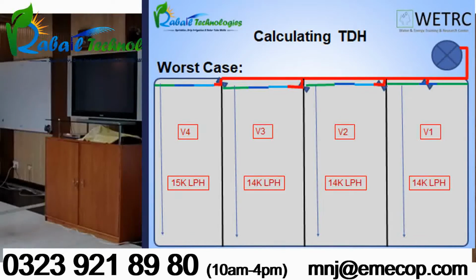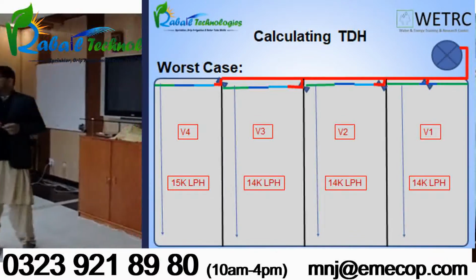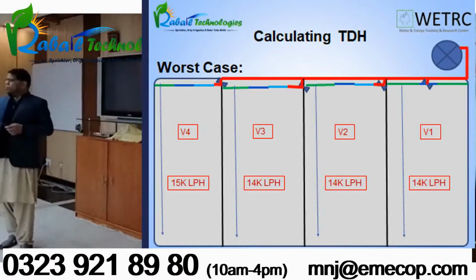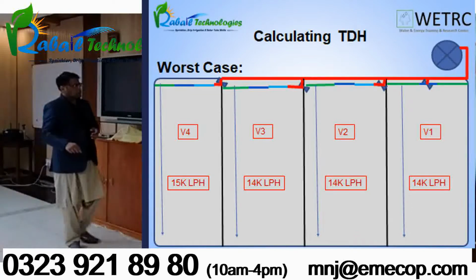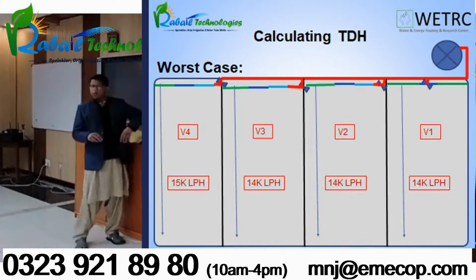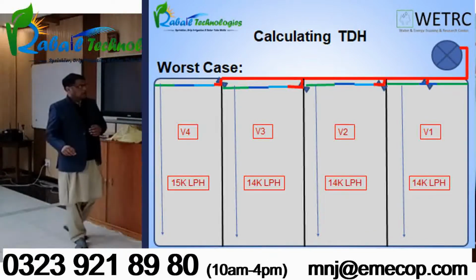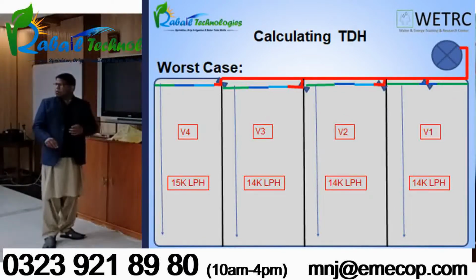And the highest flow is for V4. So I need to use the Hazen-Williams equation for calculating the friction loss in this zone or in this valve. So the length will be from here to here. Flow rate is 15,000 liter per hour.